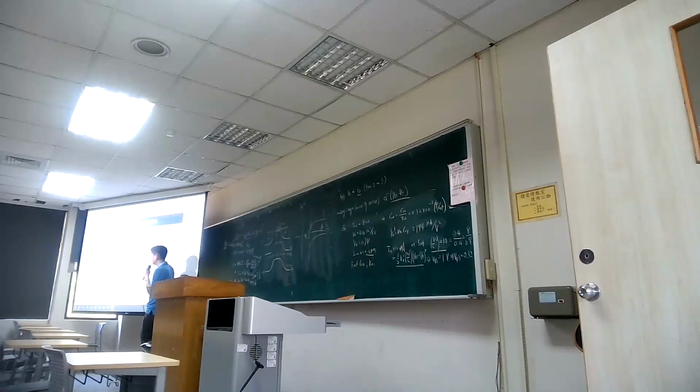So this one, EFN. Okay, so EFN and EFP, the quasi-Fermi levels, will later on combine in the bulk material after the depletion region. So here we just introduced the intrinsic level. The quasi-Fermi level will be split here because you split the majority carrier, so the majority carrier will go further down instead of staying along this state.